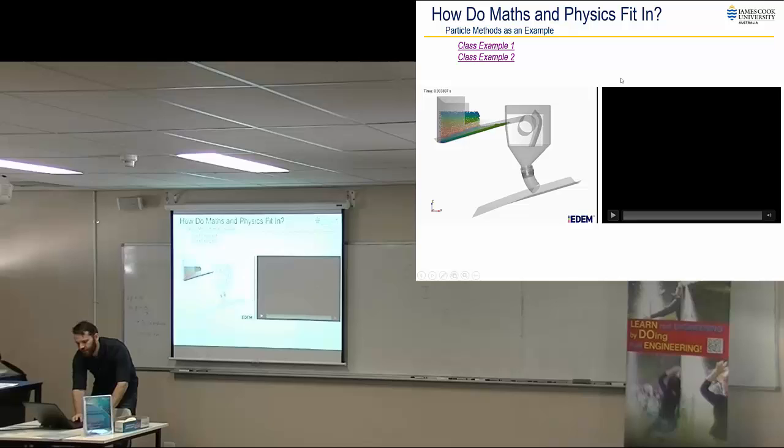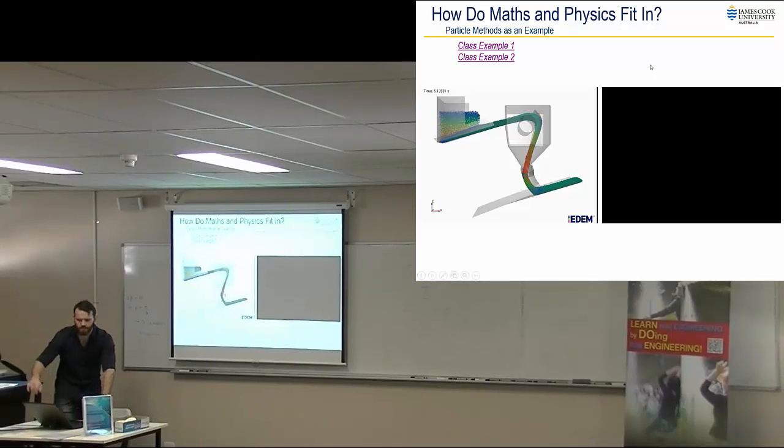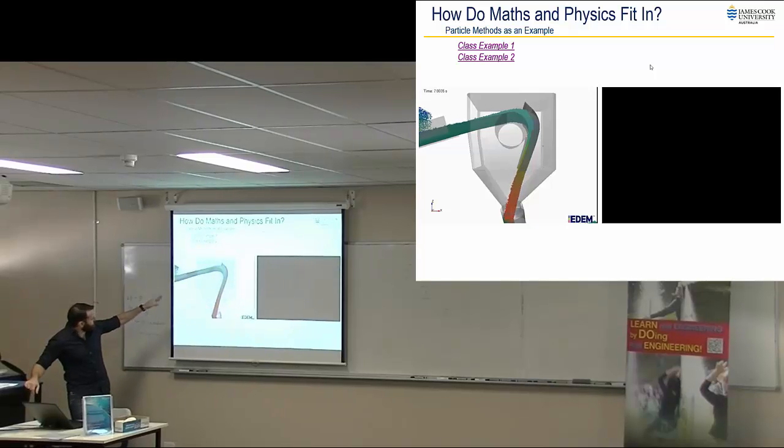Here's some practical applications of that. Is a conveyor going through a hopper system down onto another conveyor, and you want to minimise the amount of damage that the material gets, and you want to make sure that it doesn't get stuck up anywhere or anything like that. So this is an industrial application of that type of problem. You can see that there's probably in the order of almost 1 million particles there, so you've got the computer tracking them, working out which ones are hitting walls and which ones are hitting each other and all that kind of stuff. So why are they different colours?